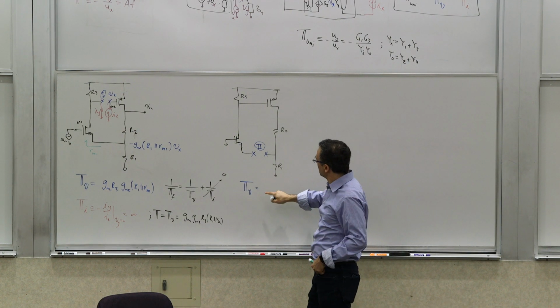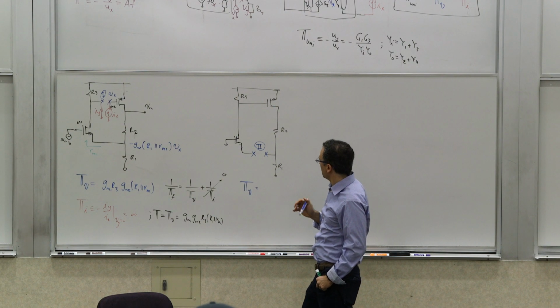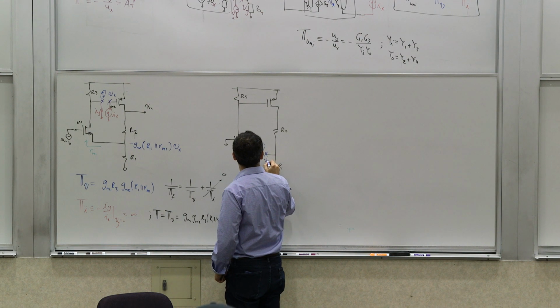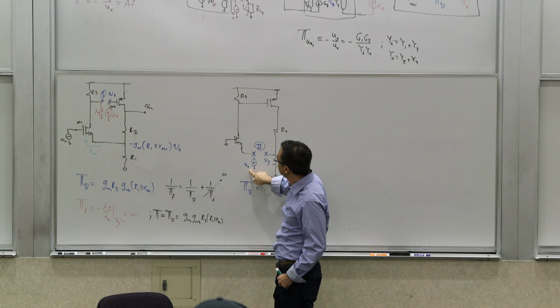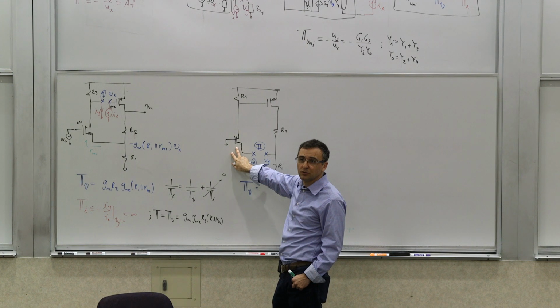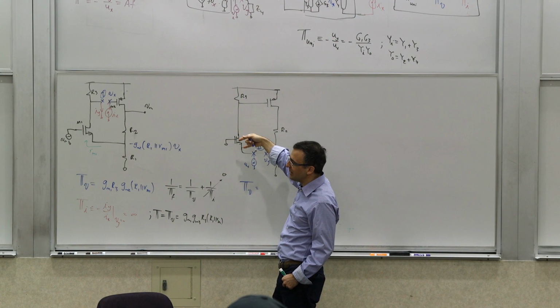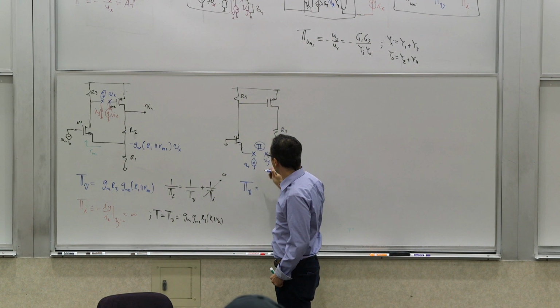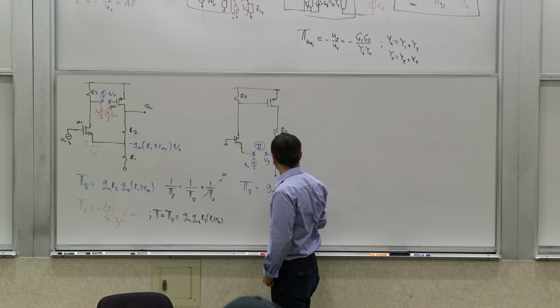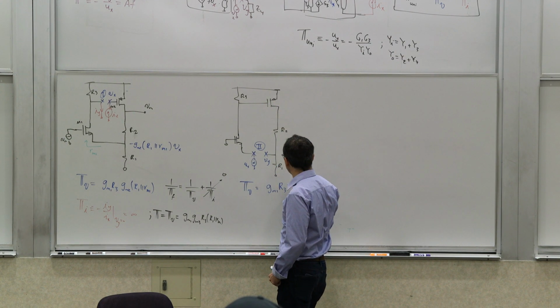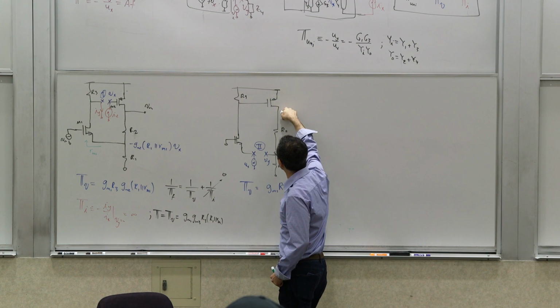So let's see. Tv, the new voltage loop gain. Apply a voltage source here, Vx, and measure Vy, right? So if you apply Vx here, it falls all across Rm1. So you get a current which is basically Gm1 Vx going through R3. Then you go through R3 to produce this voltage. Then you go through here, and then you have a Gm2 to produce this current.